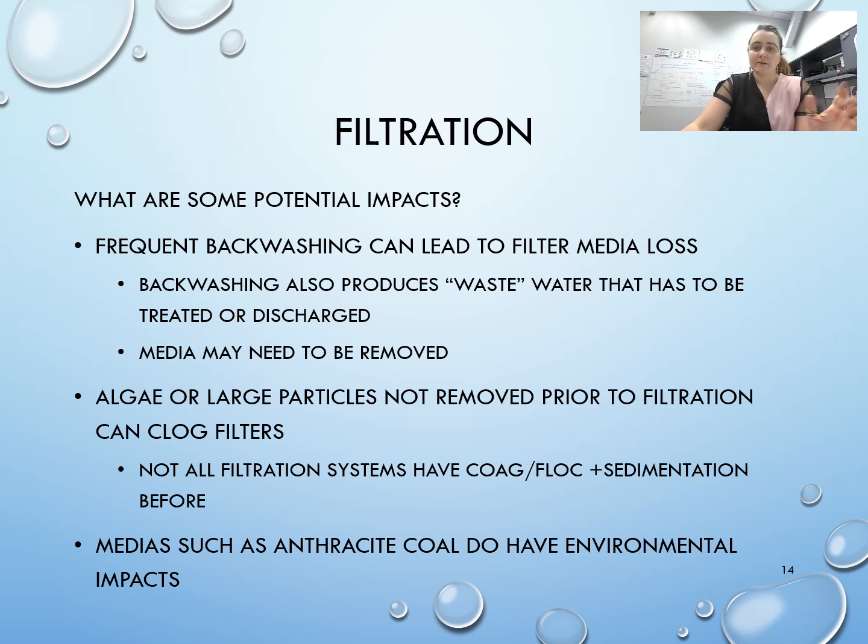And then lastly, let's talk about some potential impacts, things to be aware of for filtration. Frequent backwashing can lead to filter media loss. As you push that water up through the system, you can lose media when you drain it away. You're not just draining away water. So that's important. So media may have to be removed and cleaned. You may have to process the backwash water. So the water that comes out of a backwash and that is drained has ugly things in it that we don't want. And so there's going to have to be some kind of treatment or some kind of discharge permit associated with that.